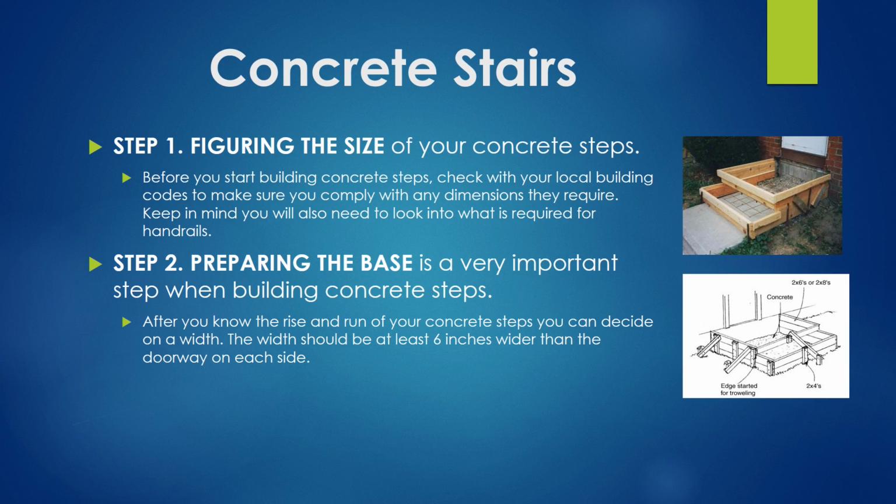Step 2 is preparing the base, and it is a very important step when building concrete steps. After you know the rise and the run of your concrete steps, you can decide on a width. The width should be at least 6 inches wider than the doorway on each side.